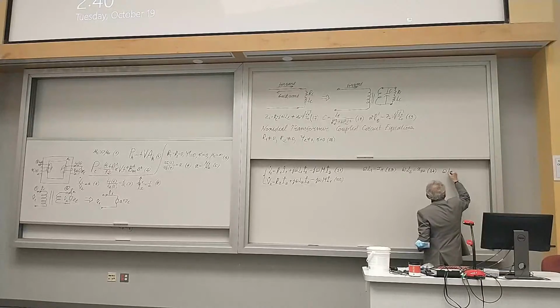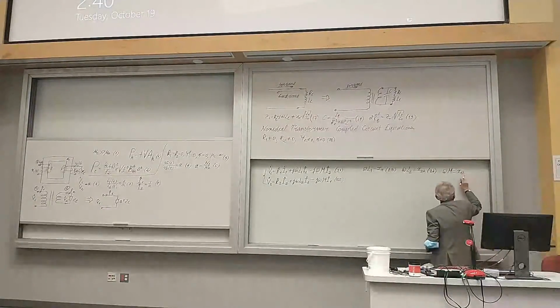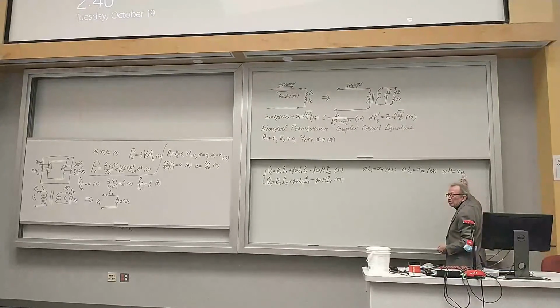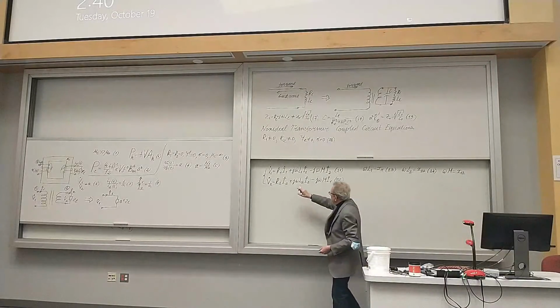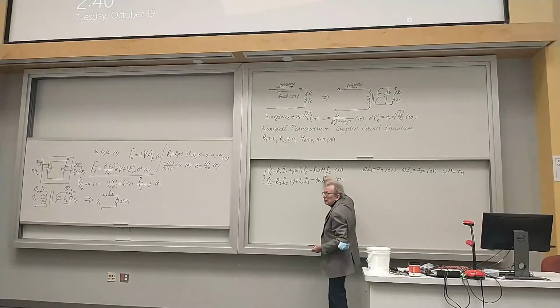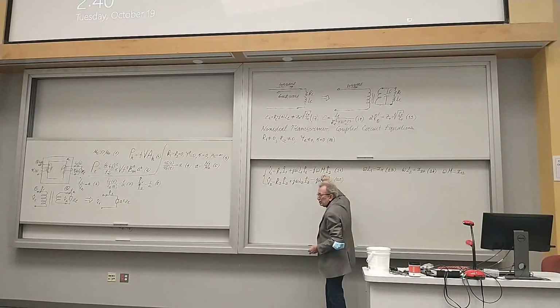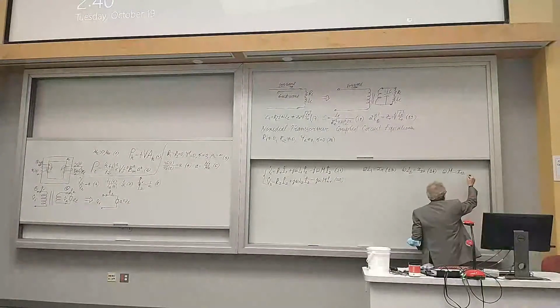And this product is called mutual reactance. And we use subscript 1, 2 for similar reasons. In the case of the primary winding, it will be the voltage induced in the primary winding by the time-varying magnetic field, another way to say, created by the current in the secondary winding. That is why we use subscript 1, 2.